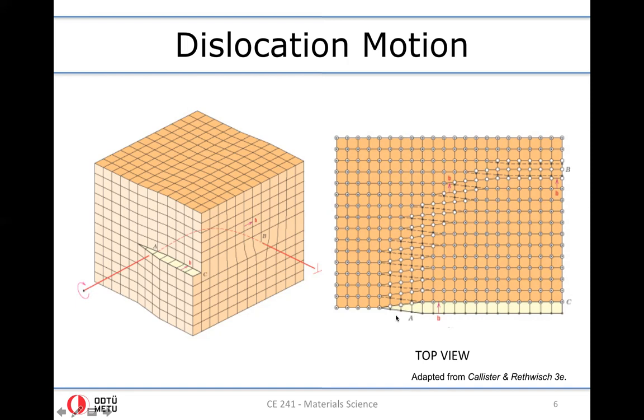As you see, as probably already discussed in chapter 4, the imperfection is in the neighborhood of the dislocation line, while the region where the dislocation has already moved is perfectly crystalline. We don't observe any mismatch here, and also the domain of the material where the dislocation line is yet to pass is again perfect. So you see the dislocation front is actually the region where we have the mismatch of the positions of the atoms with the perfect structure of the crystal.